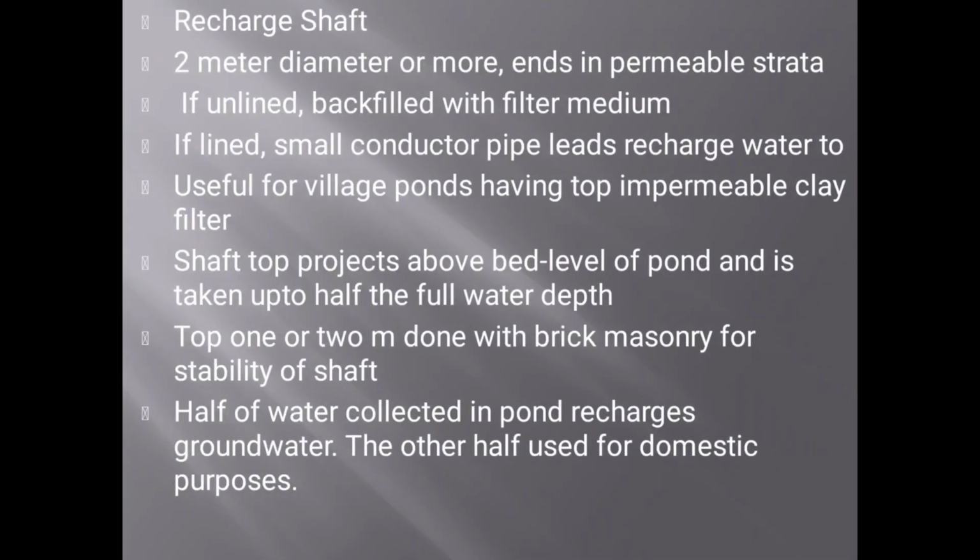Next method, recharge shaft, 2 meter diameter or more, ending in permeable strata. If unlined, it is backfilled with filter medium. If lined, a small conductor pipe leads recharge water to it. Useful for village ponds having a top impermeable clay layer. The shaft top projects above the bed level of the pond and is taken up to half the full water depth. The top 1 to 2 meters is done with brick masonry for stability of the shaft. Half of the water collected in the pond recharges groundwater, the other half is used for domestic purposes.